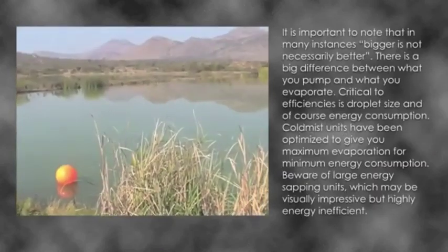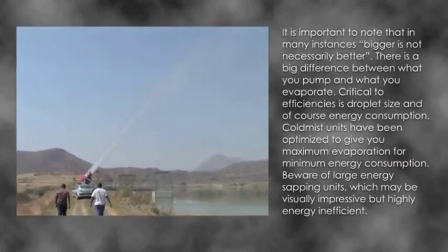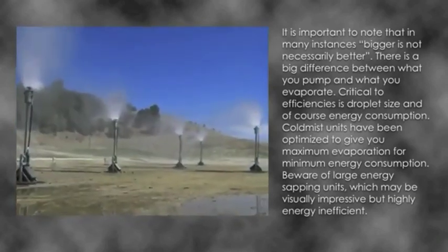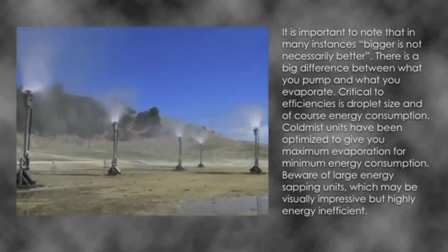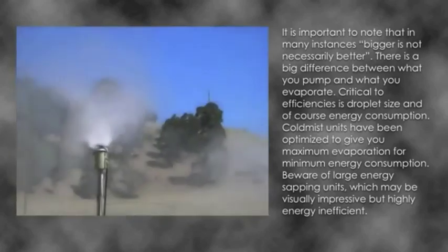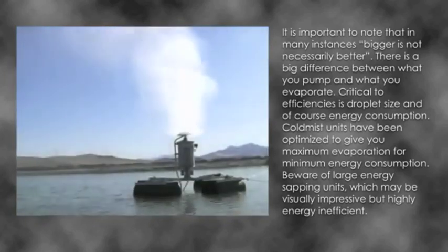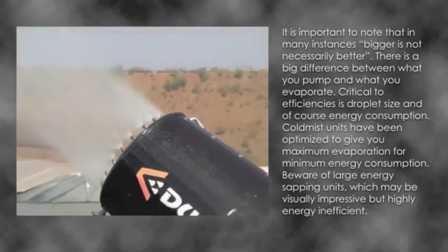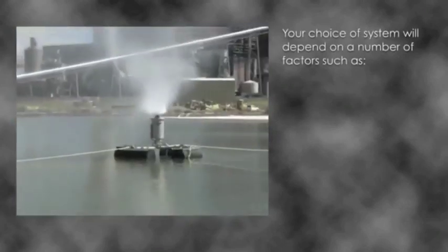It is important to note that in many instances, bigger is not necessarily better. There is a big difference between what you pump and what you evaporate. Critical to efficiencies is droplet size and of course energy consumption. Cold Mist units have been optimised to give you maximum evaporation for minimum energy consumption. Beware of large energy sapping units, which may be visually impressive but highly energy inefficient.